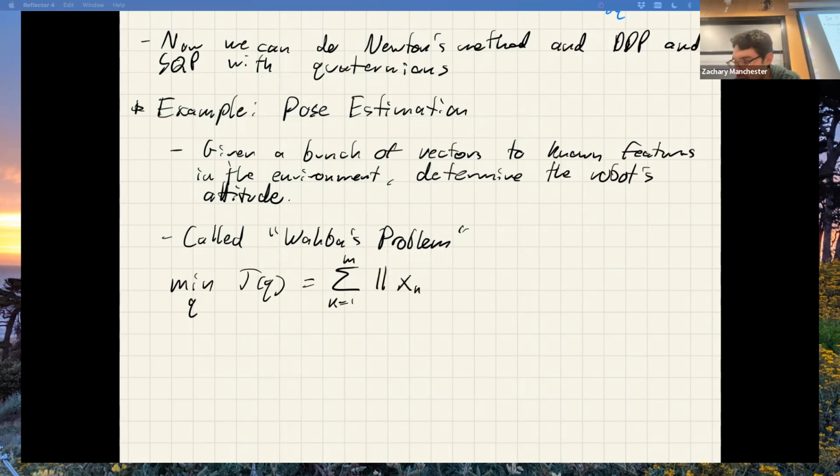So if I have the version in the world frame, which I'm going to write with an n superscript, it's got to match as closely as possible. This is going to be the rotation matrix, big Q, computed from the quaternion, which we did last time. Rotation times the body frame version, right? So the rotation is from body to world coordinates. XBs are the body frame ones that I get from my camera. XNs are the world frame ones that I get from my map. And that's it, right? Q times XB should give me XN. I write down a least squares loss on that and minimize it.